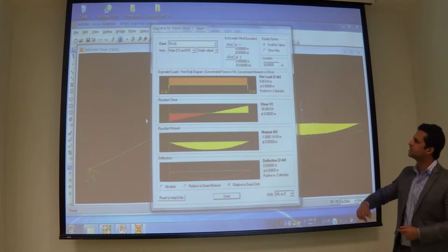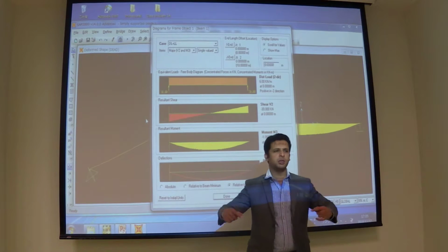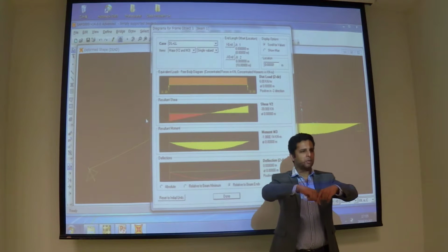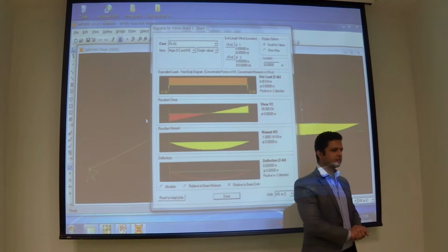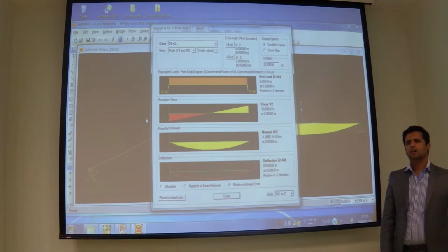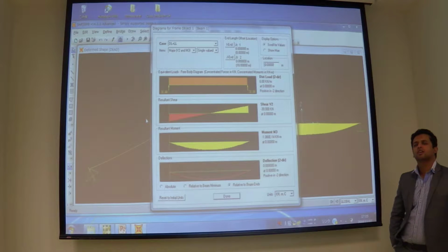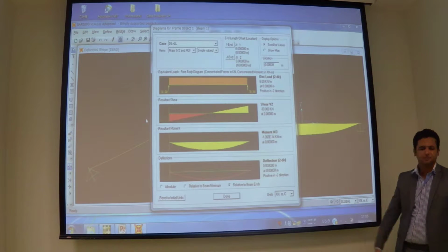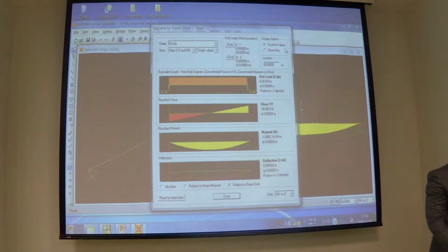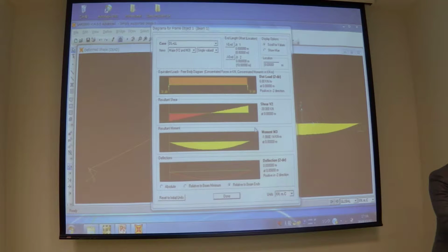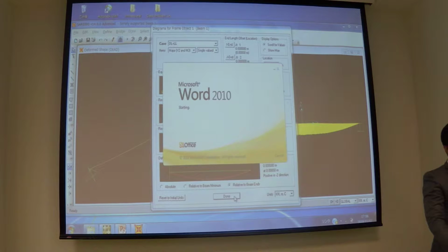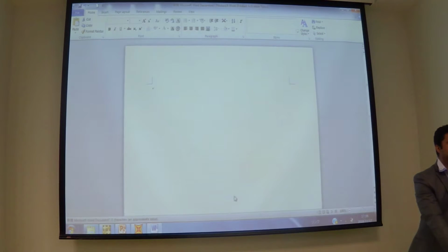Okay, calculate the moment at the center now. Now you know the beam. The beam is simply supported. Find out the moment at the center. How much will that be? No, at the center, maximum moment 60 into 5. 75. 75.